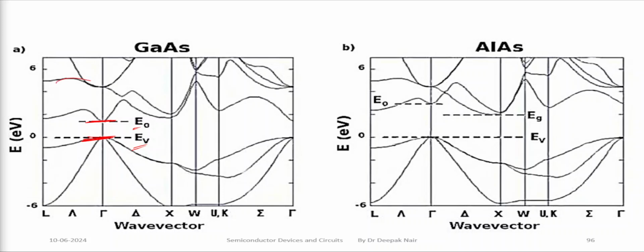These energy bands are associated with the complete lattice, or arrangement of different atoms and molecules inside the semiconductor. Out of all these energy bands, the closest energy band gap is called the energy band gap EG, the gap between EC and EV. Similarly, for different types of semiconductors, you will find different types of valleys and difference between the EG and EC.